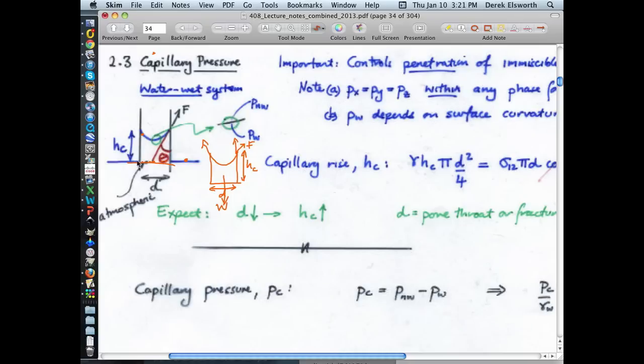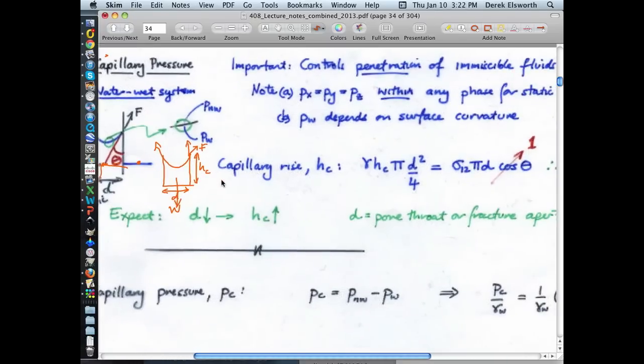So two things. We know that this is atmospheric pressure. We know that since we can go from this point to this point here, which is on the same horizontal line, so this has to be atmospheric pressure. We can therefore cut it off at the bottom and represent it as this. And now we can treat it as a free body, and we can just balance forces. If we balance forces, then what are those forces going to be?